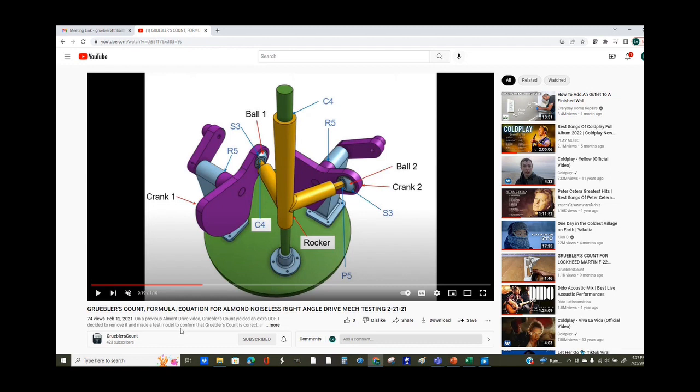Well, that's where you put a universal joint in. Do you see this mechanism here? This is before 3D printing. I machined all this. This is a landing gear for a jet fighter, an A4. To let it dampen for this model, I put an air cylinder here. The air cylinder has a spherical joint at the end here, and since it's spherical, this rod actually rotates inside. But down here, to keep the body from moving, I put a universal joint. That is anti-click-clack. That prevents it from rotating. So that's how you do it.